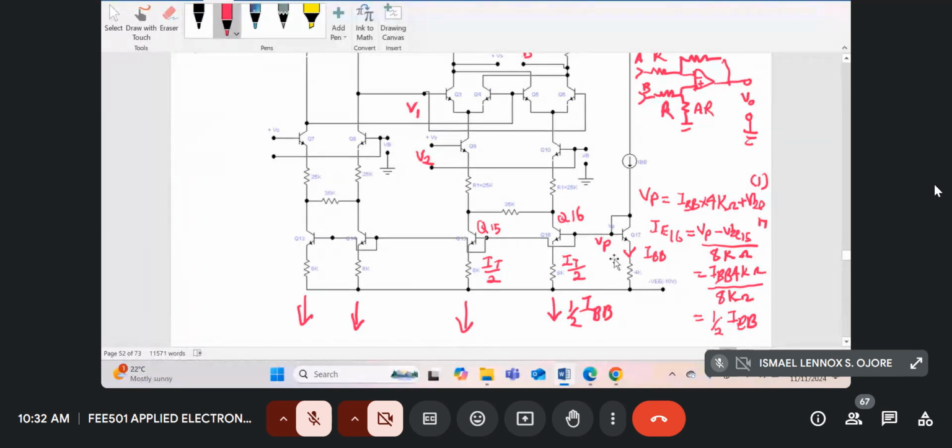All right. And then the base voltage, which I'm calling VP, would be the drop across the 4K resistance at the emitter of Q17 plus VBE. And this voltage is VP. So the same voltage VP appears at the base of Q16. So to go to the emitter voltage of Q16, I have to drop VP minus VBE of Q16. Now the VBE is identical because this is fabricated in one chip. Okay, this is an IC chip, so this is fabricated in the same silicon wafer, so the VBEs will be identical. So it won't affect.